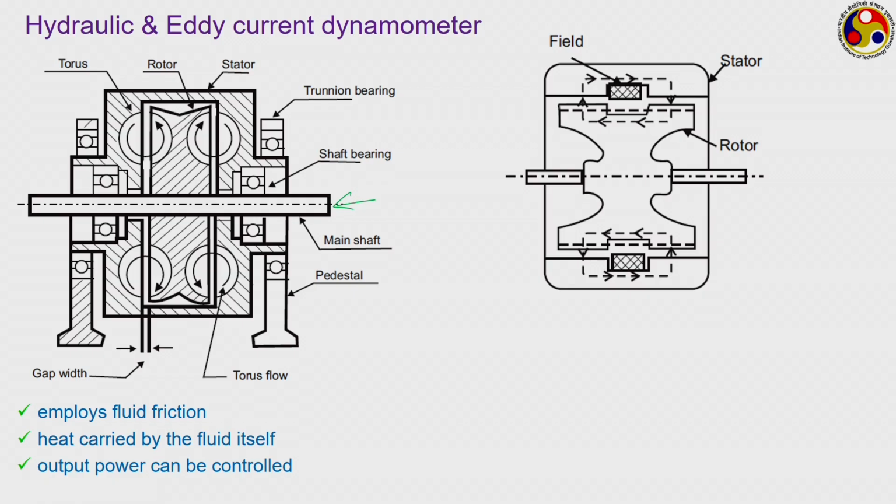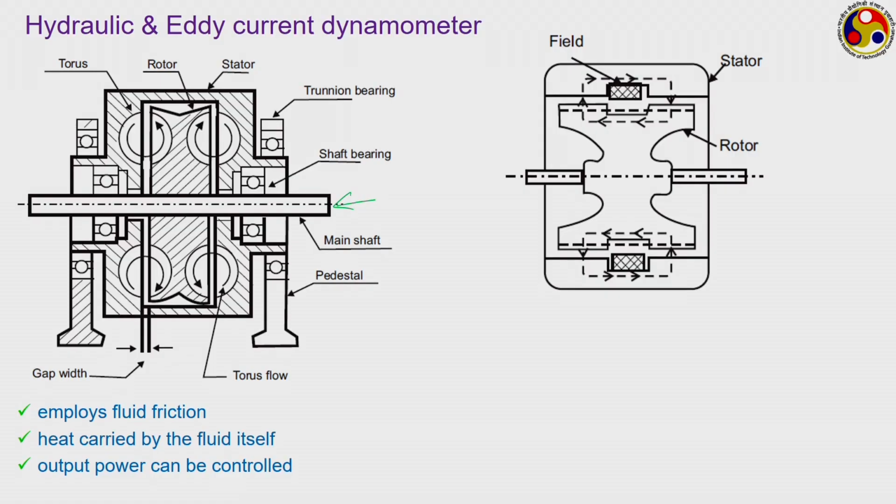And the final device to talk about is the eddy current dynamometer, where you have a stator part, you have a rotor part, and just the way any common generator works, the eddy current dynamometer works the same way. As the magnetic field is there, as the power is applied, it produces a voltage output, and from that voltage output we can get a measurement of the corresponding torque.